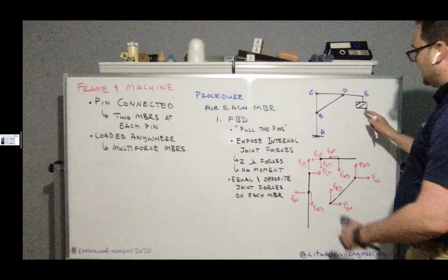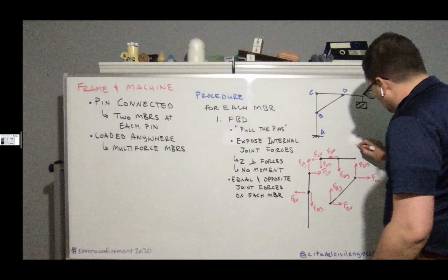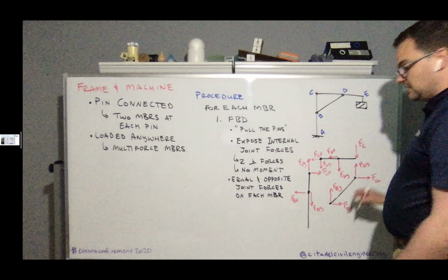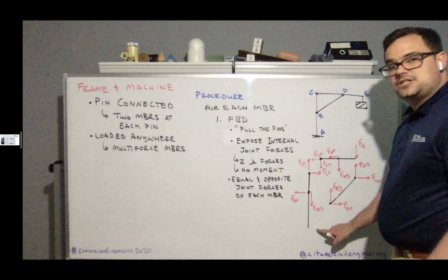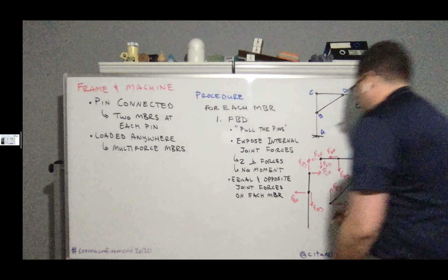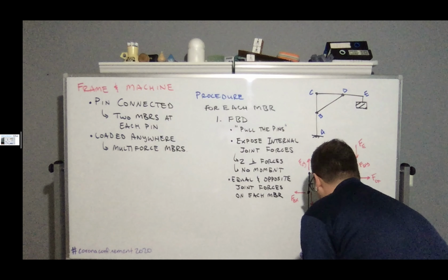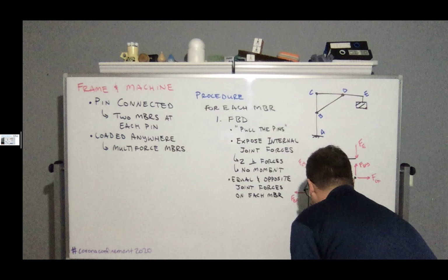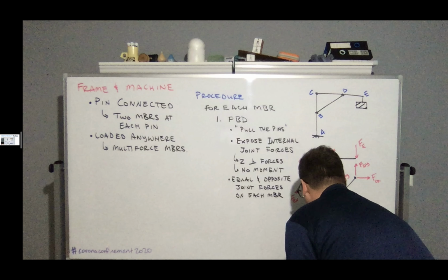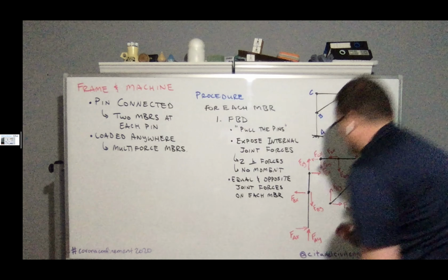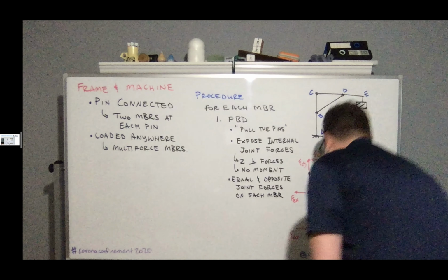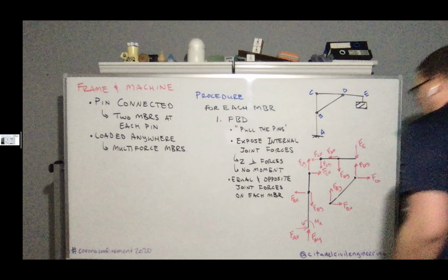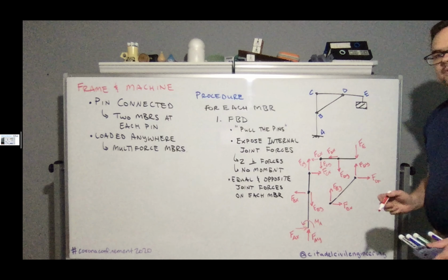Well, I've got my load out here, so I would probably have a force at E that's driving the load. And then I had a fixed connection down here. And so a fixed connection in 2D is going to give me a vertical force, FAY, FAX. And because it's also fixed, it needs a moment, M about point A, as my moment reaction.